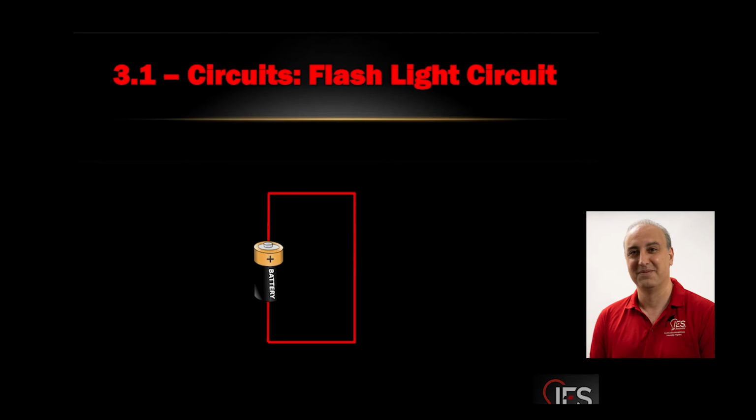So we put a resistance in that path to control it. It could be a resistance or a piece of equipment. Everything has resistance. In the flashlight circuit, we actually put a light bulb in that wire, and that becomes a useful usage of electricity. Electrons are flowing through the light bulb much like they were flowing through the wire, but the old incandescent light bulbs were actually a very high resistance designed to emit light when they got hot, so they would glow. Ever tried to change an incandescent light bulb right after it turned off? Burn your hand pretty quickly, right? It was hot, because we were heating the tungsten element inside the light bulb, and that would glow and give us light. LEDs are diode based, so they're semiconductor based, a very different system. They don't get hot and they don't use as much electricity. But we're focusing on this right now.